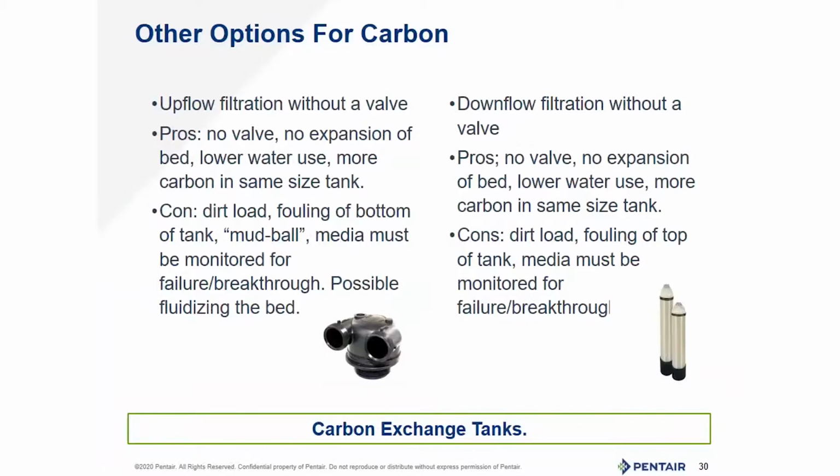Okay. You can do this also with downflow in and out adapters. Same pros: no valve, no expansion in the bed, lower water use, more carbon in the same footprint. Same cons: dirt load falling at the top of the tank. Media must be monitored for failure and breakthrough. And these are quite often done in a lead lag scenario so that when one starts to fail, you have another one to pick up.